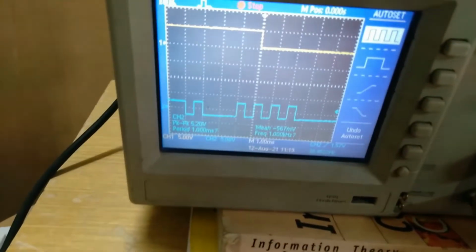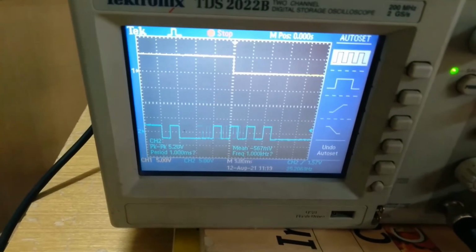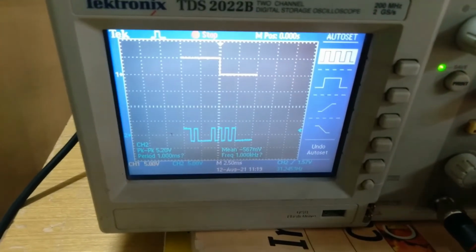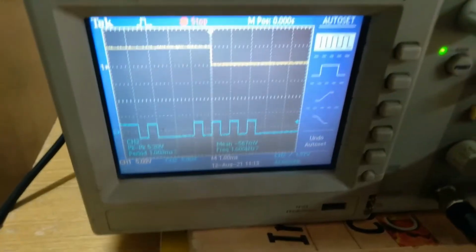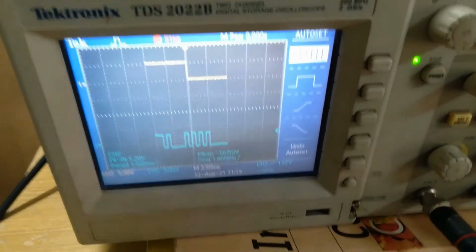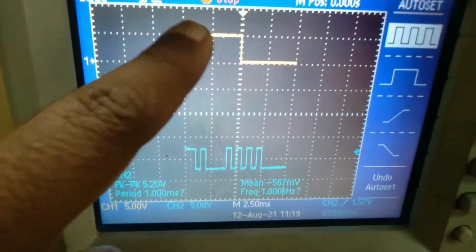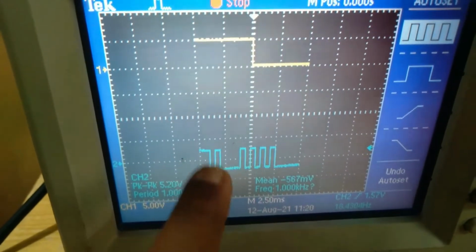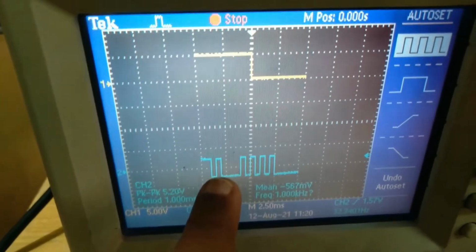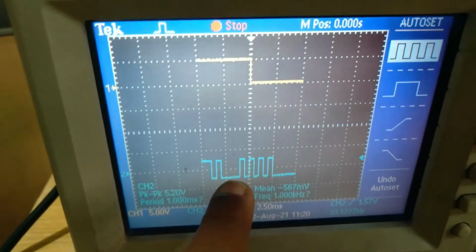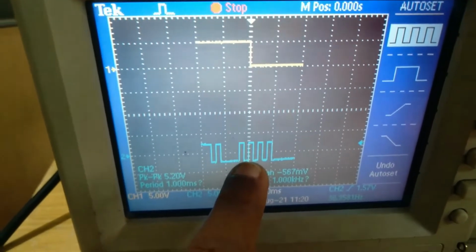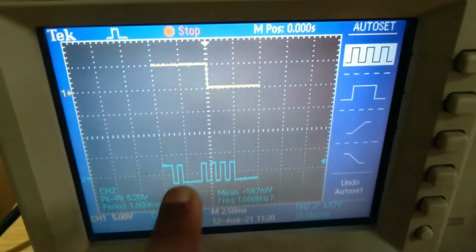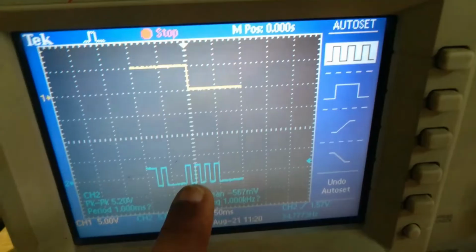So you can just see that in one bit duration, there are multiple PN sequences which are being generated. For example, if I observe here, this is 1 bit which is there for your data bit, but in that data bit you have 1 1 0 0 1 1 1 0 0 0 1 and 0. So this is the PN sequence. So in 1 bit pattern, there are multiple PN sequences which are being generated, right?